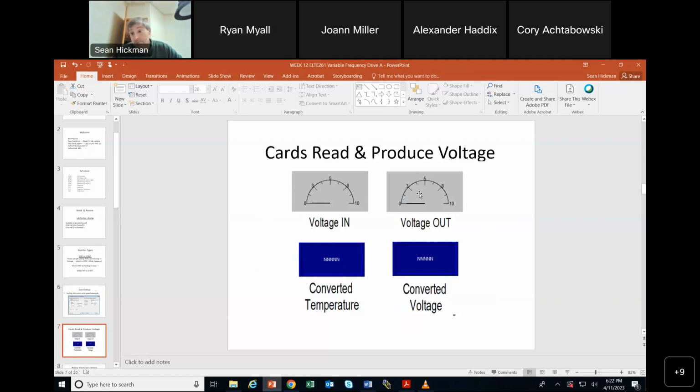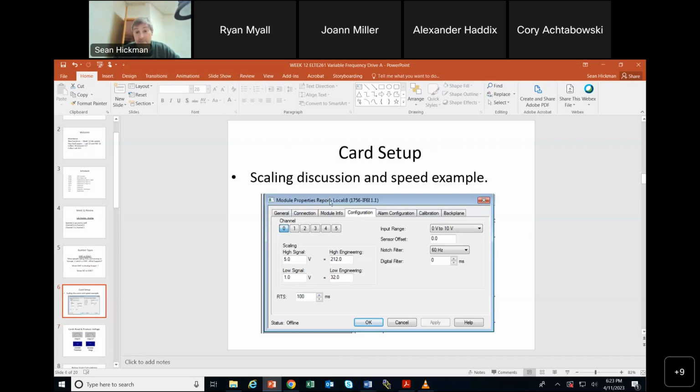All right. So let's look at the voltage out. You could set up the voltage out. I had you take the temperature and convert back to voltage out. What you could have said was, hey, I could have said, pretend this was my output card. All right, pretend this was my analog output card, not my input card, my analog output card. And I could have done my scaling 32 to 212, push out to my output card 1 to 5. Okay, does that make sense what I just said? Yes or no?